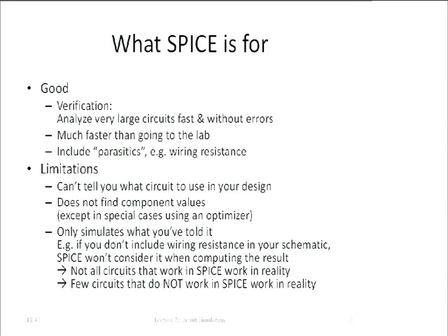So the final thing that's very important, SPICE, of course, simulates. The simulator can know only what you tell it. So again, for example, wiring resistance, if you do not put wiring resistance into your model, into that schematic that you tell SPICE to simulate, then SPICE assumes happily that there is no wiring resistance. Or if you do not tell it, well, the component that I'm using there, the resistance could be a little higher or a little bit less than the actual value that I'm putting in there. Well, SPICE doesn't know about that and ignores it and simulates happily with whatever you stuck in.